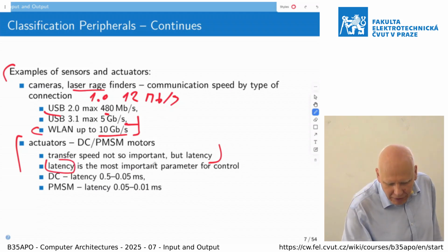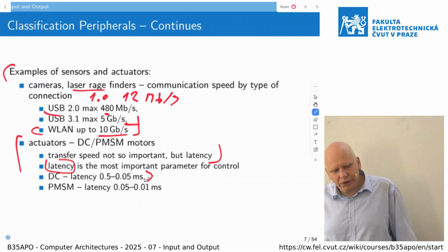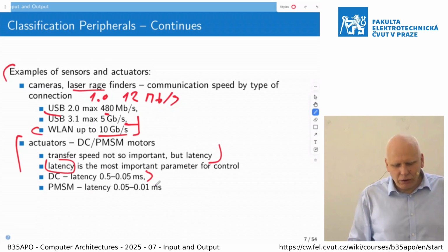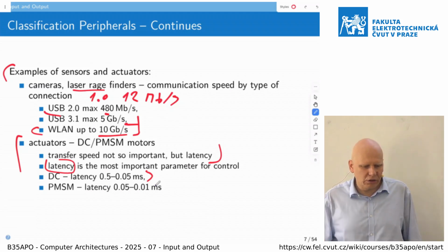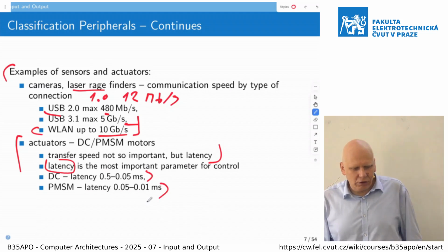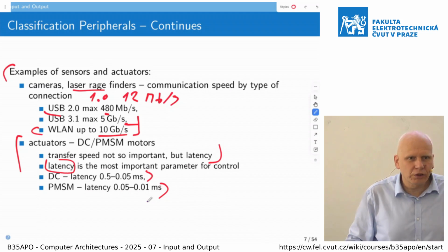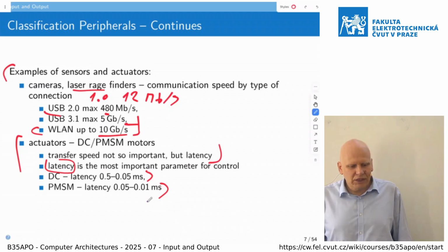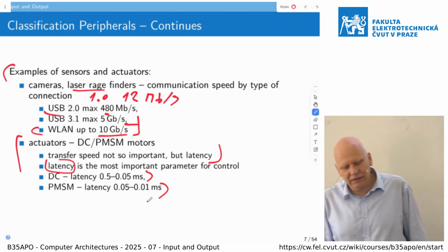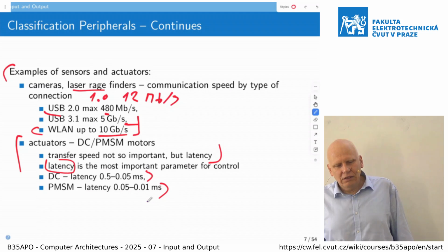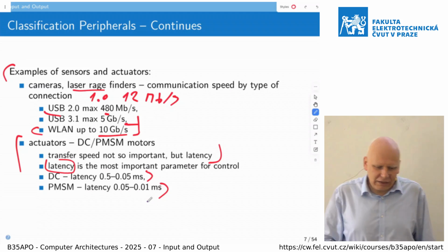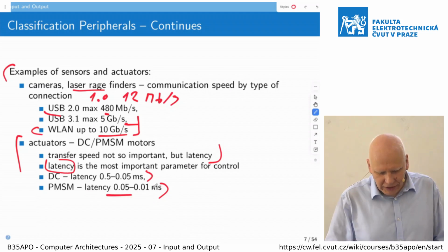And if we speak about DC motors and their control, then some latency, little below 1 millisecond, is again enough to control the robot. But if you want to do the full field-oriented control of permanent magnet synchronous motors and such stuff, which we do, then you need to go to something like 4 or 8 kilohertz and even faster. We have a commutation coprocessor which runs at 20 kilohertz for those kind of applications.